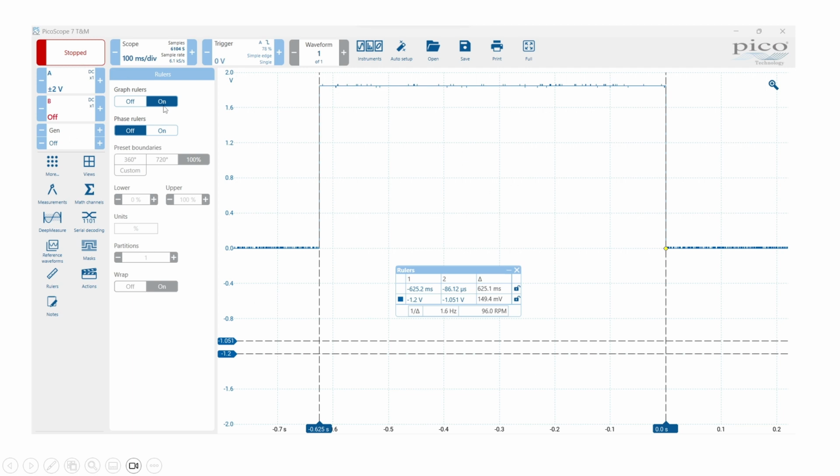In our Picoscope app, we can set the time per divisions according to the time that we are getting. So I have set my time per divisions scale to 100 milliseconds per division, and then I have set the amplitude to plus or minus 2 volts per division, and I am using the trigger option to basically stop the screen from running when a falling edge occurs. So as soon as this edge occurs, the screen is stopped, as we can see here.